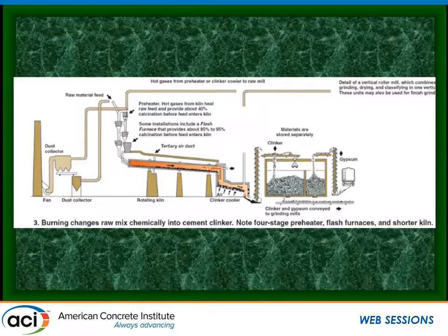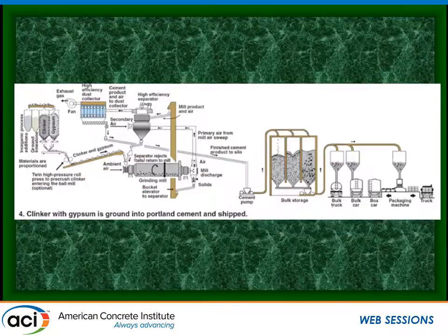But the iron left over from the steel belts stays in the kiln with the material. Now, iron is a normal component of cement, somewhere in the range of 3%. So when we burn tires as fuel, we have to account for the amount of iron that's going to be in those steel belts to keep that same 3% going. So it's a constant balancing act of all of that chemistry.